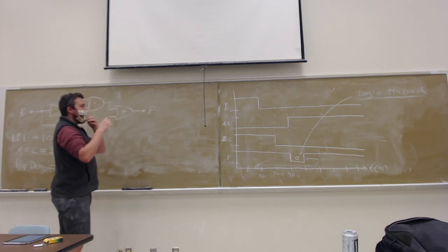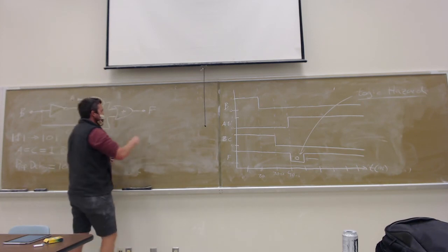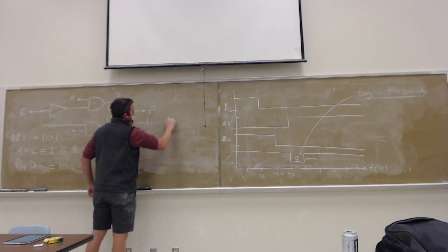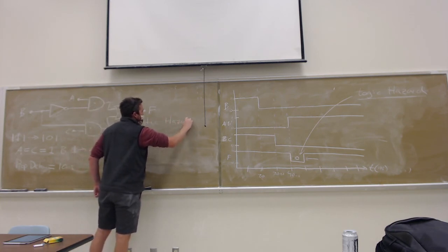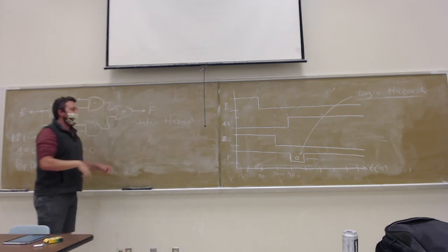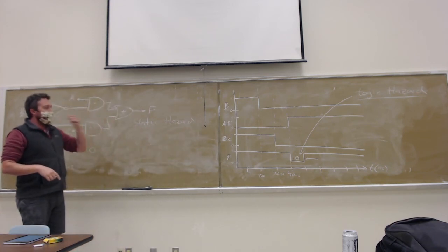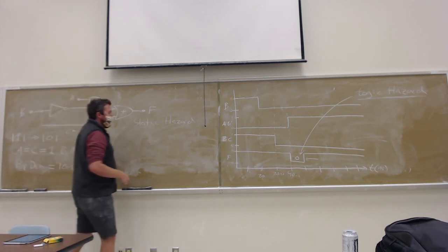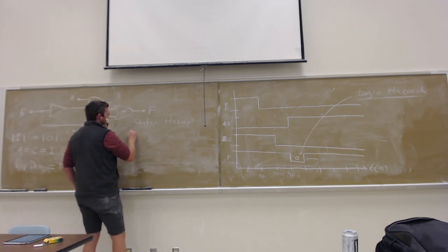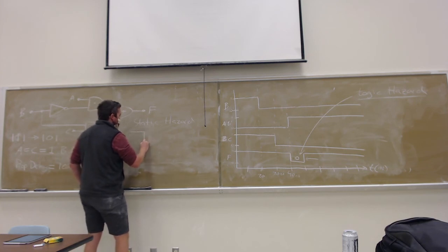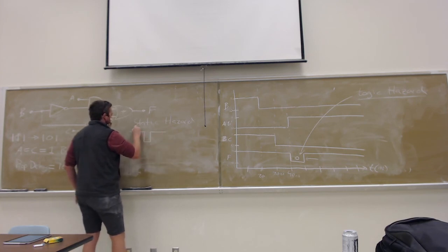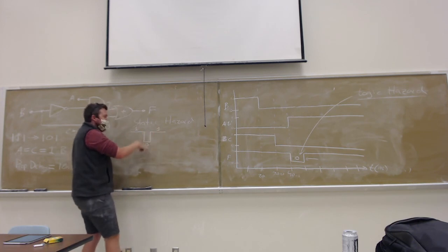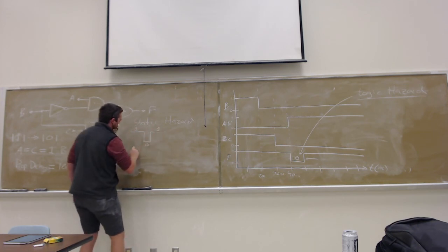So, there are two types of logic hazards. There's what's called a static hazard. A static hazard is when the unwanted bit only occurs once, when the error only happens one time during the transition. So, for example, if we are at 1 and we go to 0, so that was 1, that's 0, that's 1, where we should have been 1, but we momentarily went to 0 and then came back, and that only happened once.